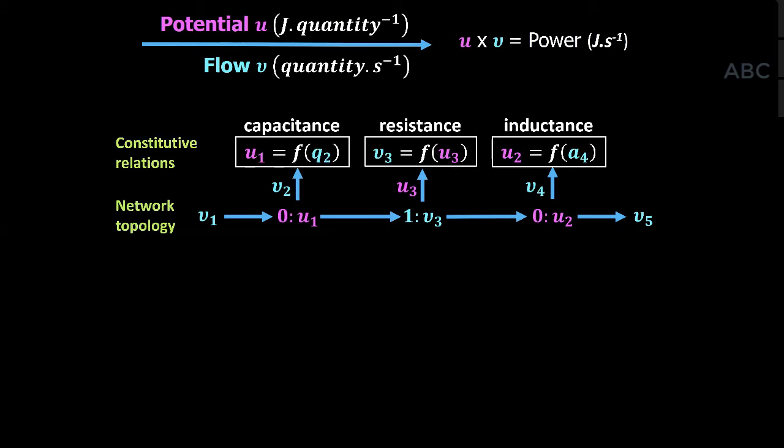Now, the next thing you do is, up to now we've been talking about transmission of energy, but now you need to think about what you do with energy, and you really only do two things. You either store it or you dissipate. And when you store it, you do that either statically through a capacitance or inductively through a dynamic storage process. So for example, for mechanics, the static storage is a spring. For electrical, it's a capacitor. For chemical processes, it's the molar concentration, and so on. And then the dynamic storage, in the case of mechanics, it's inertia. In the case of electrical systems, it's the inductance, etc.